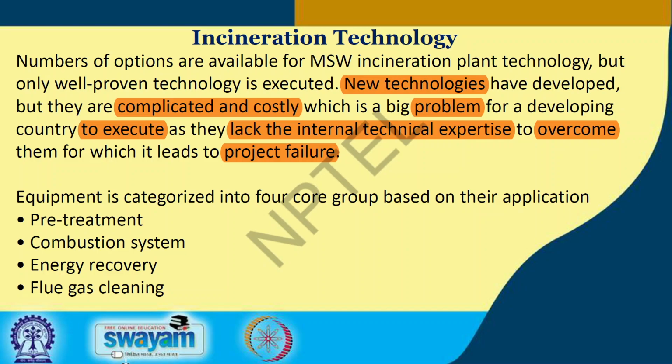Because we can't expect a continuous flow of plastic waste as feed to the incineration plant. But abroad, most of the composition of the municipal solid waste will be paper, plastic, rubber, tires. These are all combustible materials. So they can operate the incineration plant. But in the Indian scenario, most of our waste is wet waste, and we will have less plastic and paper in the composition of municipal solid waste. That's why this type of project will fail in the Indian subcontinent.